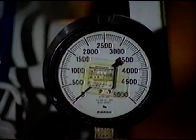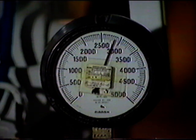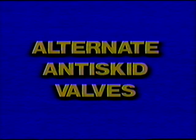If installed, the brake pressure gauge reads not more than 100 psi when the brake is released and 2900 plus or minus 200 psi when the brake is applied. Note that this test detects crossed lines in the anti-skid system. The alternate anti-skid valves are checked in a similar manner.